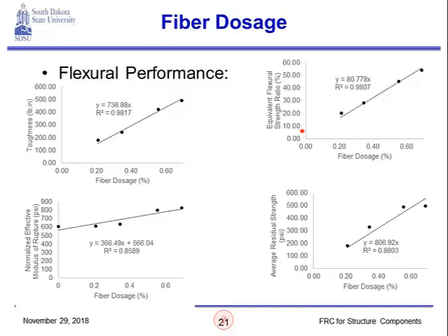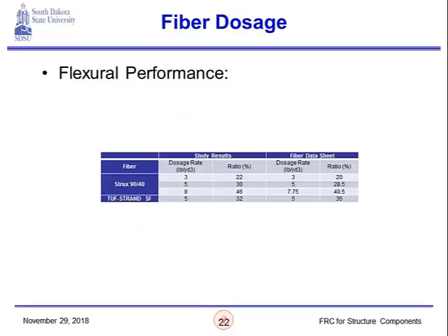that we used in our studies. But yeah, it's something that we would expect. The more fibers you have, the more bridging of cracks, and the higher the capacity of the concrete would be when it comes to tension, which means higher flexural capacity.